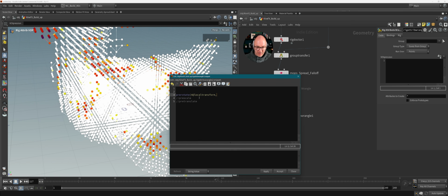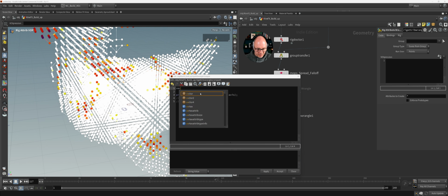And then comma, and now we need an angle that is a float value and an axis that is a vector. I'm writing these now as variables here because I want to specify the variables right now. So we can create the axis right away because we already set this up in the last wrangle. So let's say our vector axis equals v@axis. That's the attribute that we specified in the last wrangle.